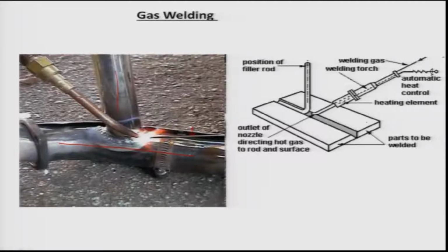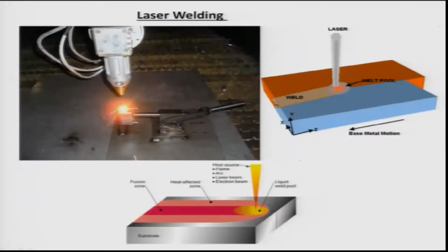Again, because welding is happening only in a small region, the bulk of these pieces remains solid, therefore there are an enormous number of heterogeneous nucleation sites present on the surface. So the only issue here is how the nucleating solids grow into the liquid. So that's the basic aspect.